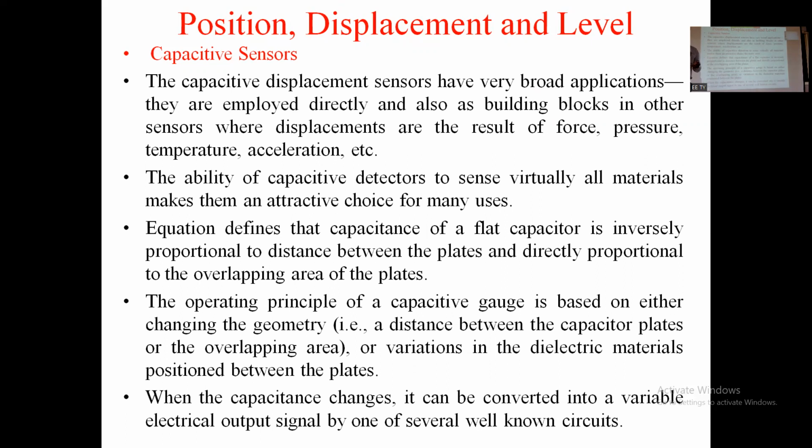It will measure the capacitance according to the equation C equals epsilon A divided by D. If D changes, the capacitance of the two plates changes, and it will be converted into an output voltage. As a result, we can measure force, pressure, temperature as well as acceleration.